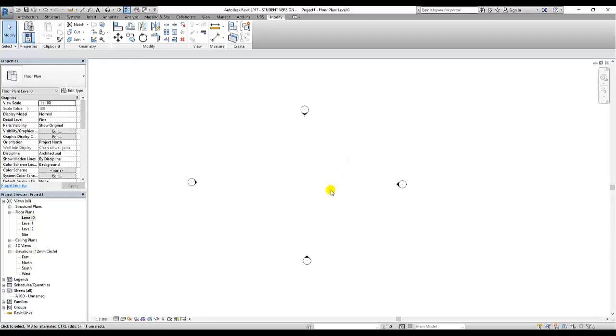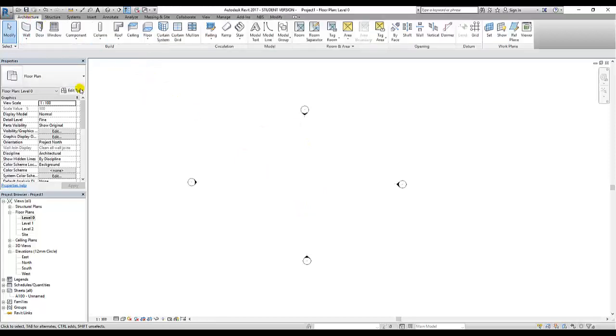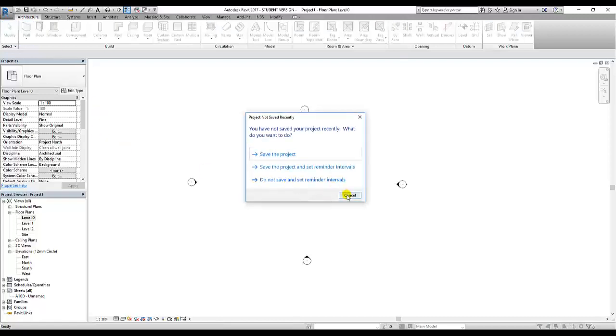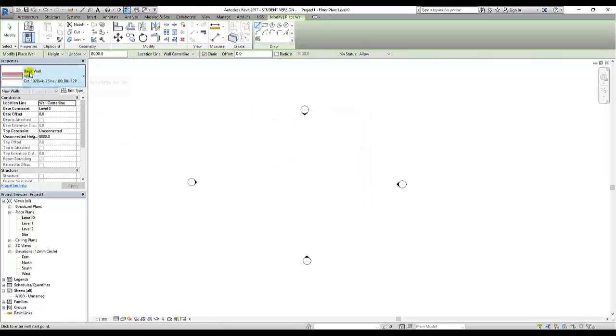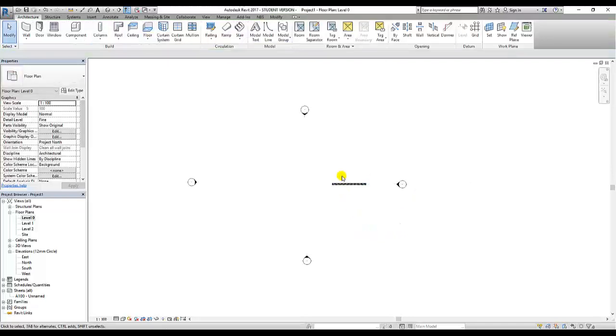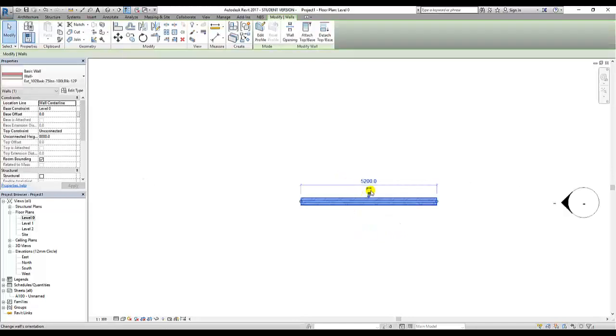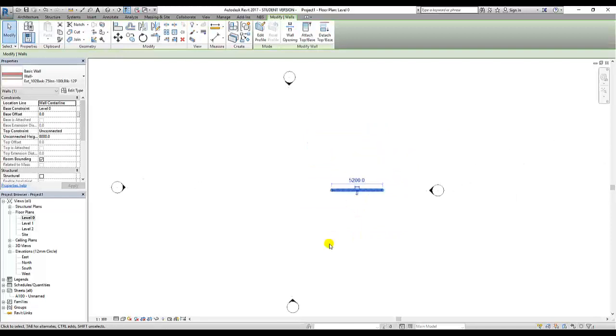Okay, Tuesday evening, and before I forget, I shall show you all how to create the curved opening in a curved wall. First up, we shall create the wall. So in the Architecture tab, I use the wall tool, cancel that, and I use this basic wall. First I'll draw a straight wall, about 5 meters long, that's fine. That's back to front. For the purposes of this, I'm going to be looking from the south elevation.